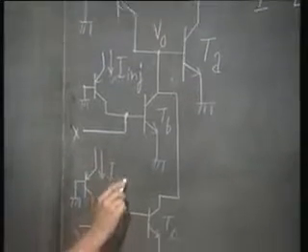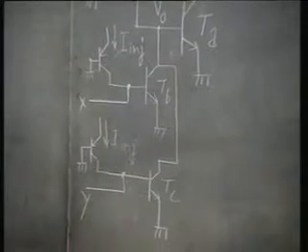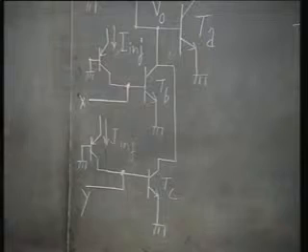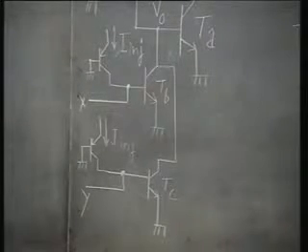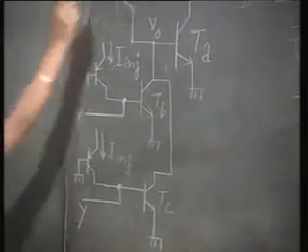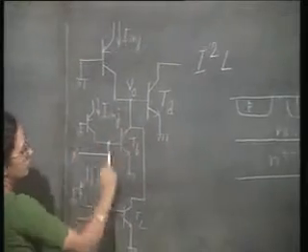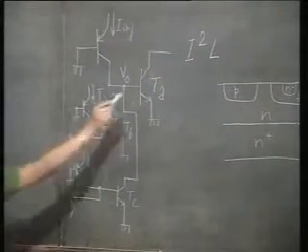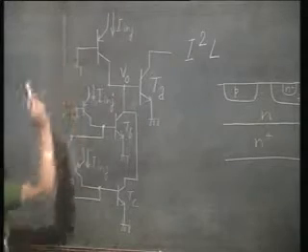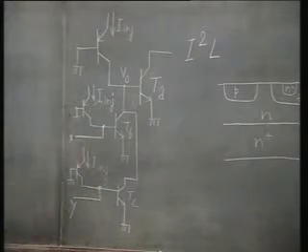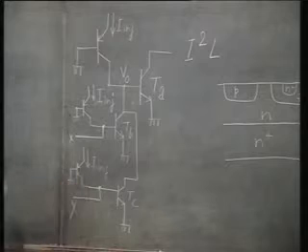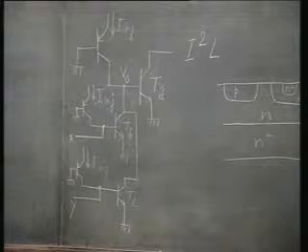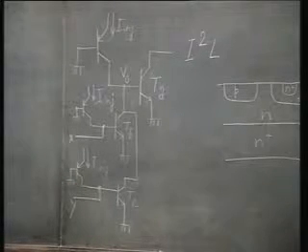The same injection current is being given to all the blocks. I have one block here, this is another block, this is another block. That is TA and this PNP transistor is one block, TB and this injection current is another block, TC and this injection current is another block. All the three blocks are identical. Do you see?